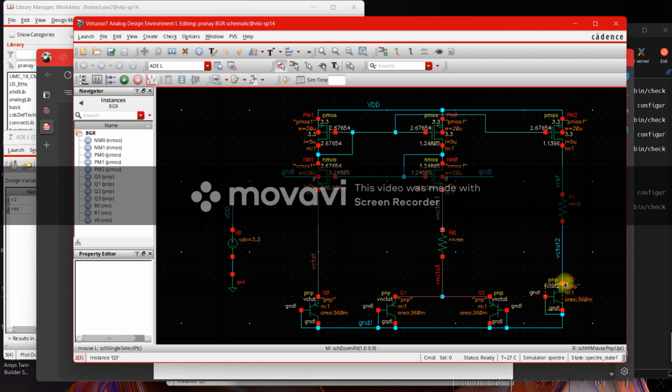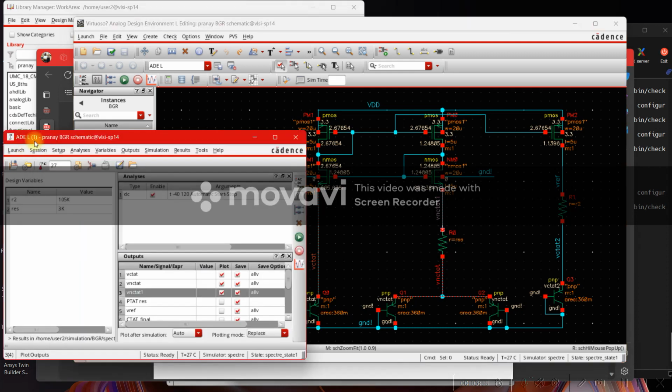And then I'm connecting the diode-connected BJT again. So from the ground, we'll get a CTAT voltage difference from ground to this point, and from here to here, we'll get the PTAT since the current is PTAT. So at this node, we'll get the reference voltage. I'll show you the simulations that I've done for obtaining these results.